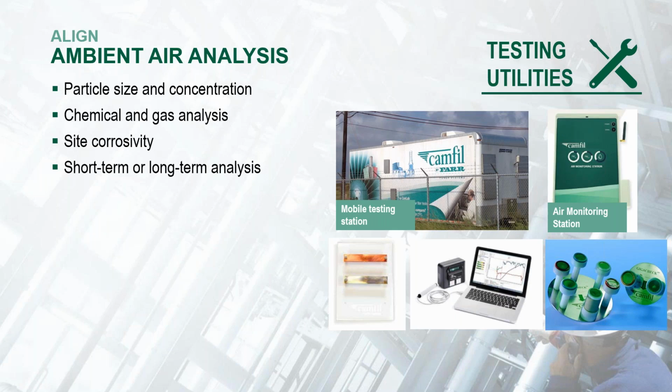So once we have the initial environmental overview of a specific site, the next step is to perform a localized ambient air analysis to determine what contaminants need to be removed before entering the engine. As Jim said, and I love his terminology, engines are air breathers. This analysis, whether it be short-term or long-term, can be done with different equipment such as particle counters to analyze the amounts of dust in the air, cascade impactors for the actual concentration of the particulate, or even mobile labs when you need to do a side-by-side comparison.